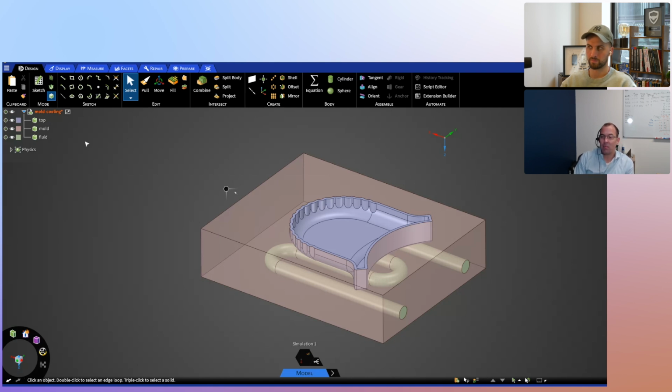And 9 times out of 10, that's going to come in as a STEP file, right? STEP and IGES, the 2 internationally known common denominator geometry files. The reality is you do lose, depending on the CAD import, maybe a 10th or a 100th of a 1,000th, and that can add up sometimes. So it's kind of a pain in the butt.